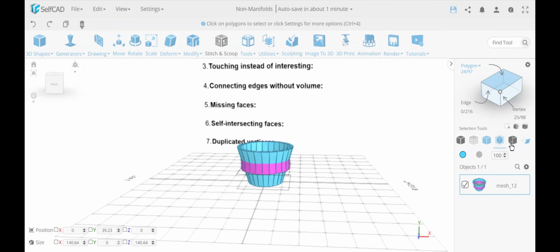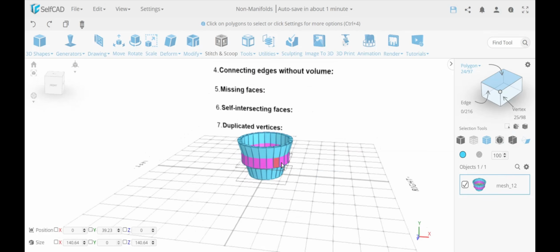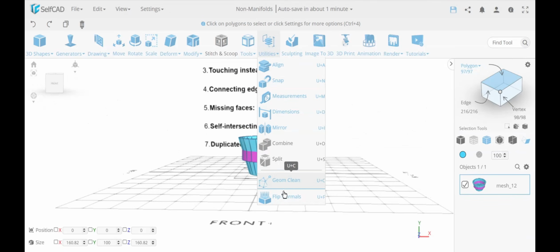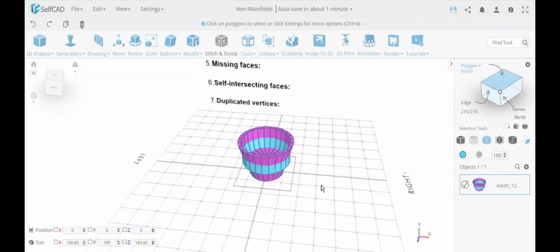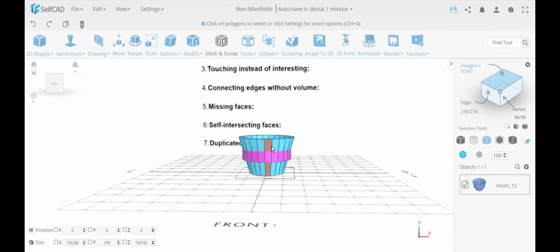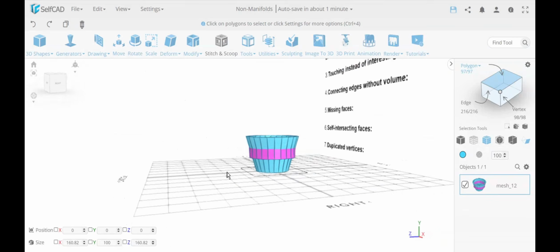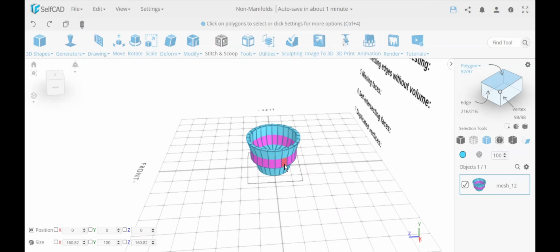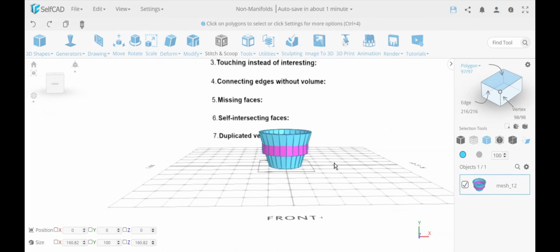Okay, so this is actually where this backface coloring can show it, because when it comes out, the inside is out. In this case, flip normals would not help, because it will actually flip everything back and will be the opposite inside out. This is because it's not a problem with flip normals, it's just that the inside is simply pushed out to the other side, and that means they also self-intersect. It just punches in the volume from the inside, from one part goes into the volume from the other part. So how do you solve that?